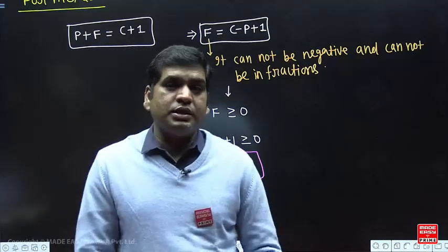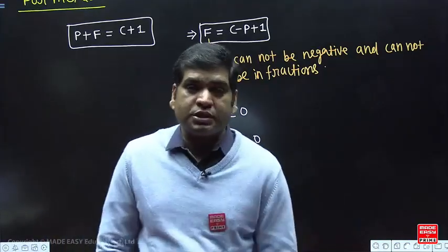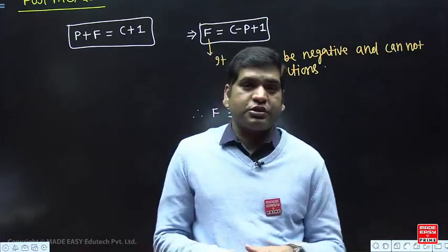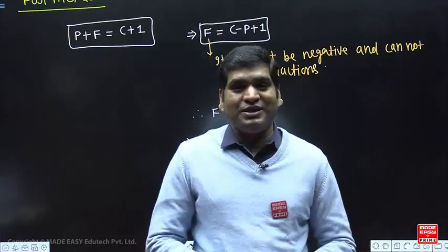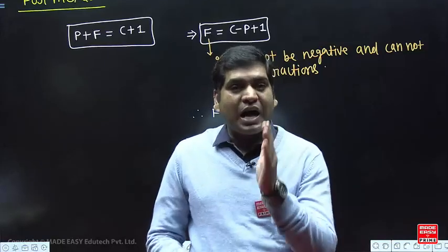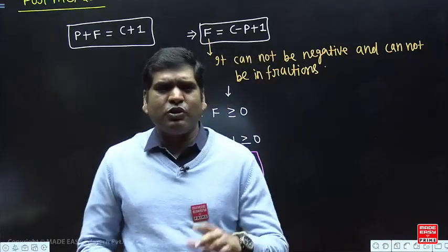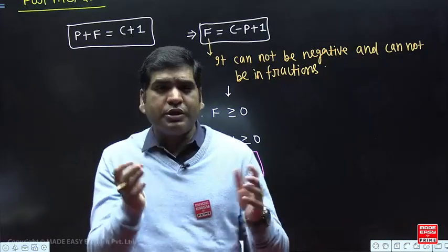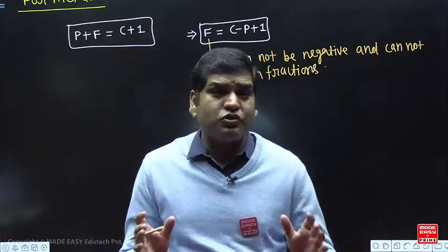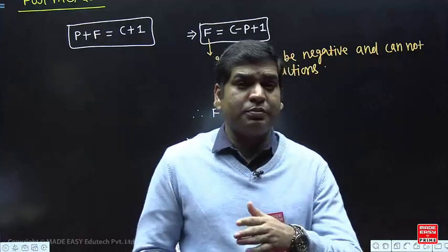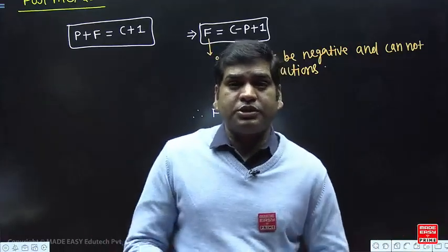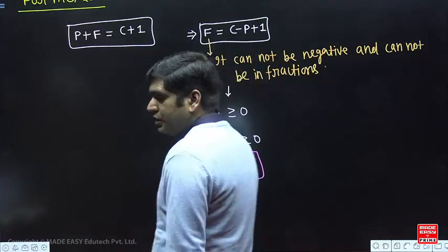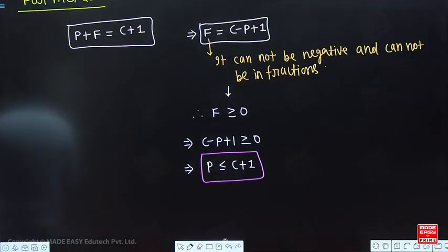And that is the reason in the beginning when I was teaching crystal structure, I told you that if a perfect crystal structure is there, meaning pure material, then you will have a sharp melting point. It means it can have only 2 phases, either solid or liquid. So it cannot have a third phase. The third phase may be a solid-liquid mixture, but it cannot have a solid-liquid mixture. Below a certain temperature it would be solid, and above that temperature it would be liquid. There is no other possibility in this case. So please note it down. This is for the pure metal.